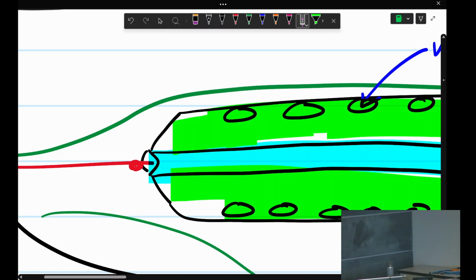So this is a real pitot-static probe. You have to look very closely to see the holes on the end of this. But how this is used, see at the end of this, this is the side that measures the actual velocity. The flow comes in like this, and it's important to get this probe aligned with the flow.